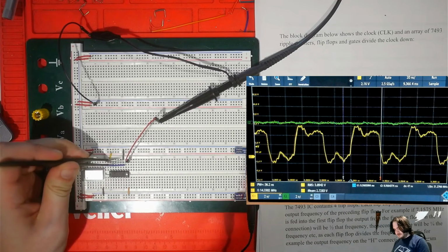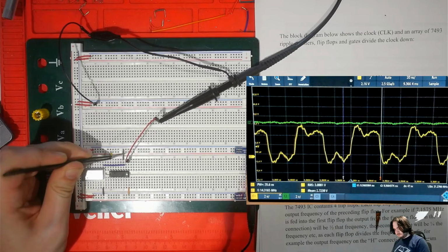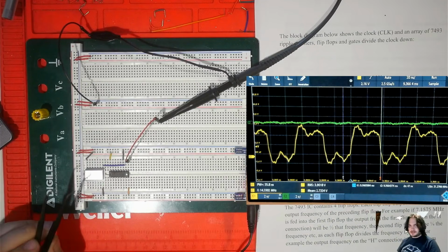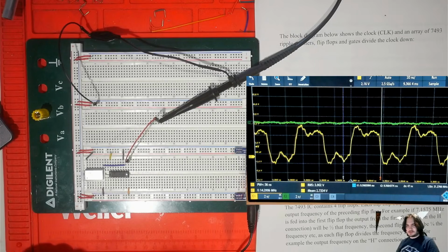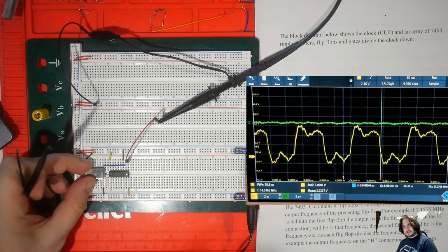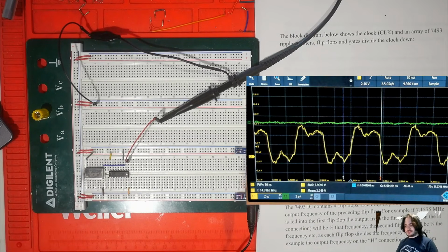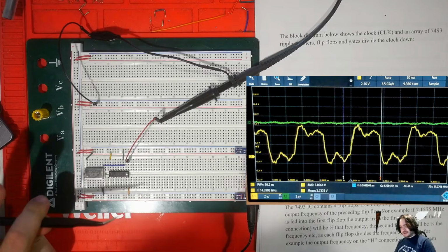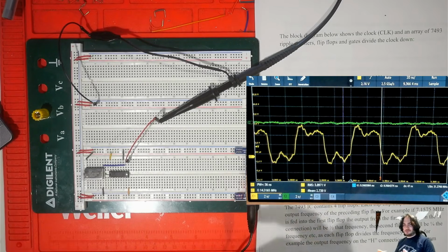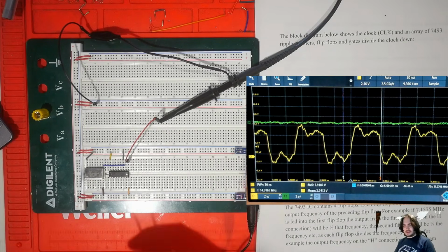So tying it low keeps this from resetting, and that's because a pin that is left floating, that's what we call it, is actually liable to drift up and down in voltage based on its surroundings, and it can drift up past the threshold on that pin just from stray capacitance and trigger the other mechanisms of the chip.